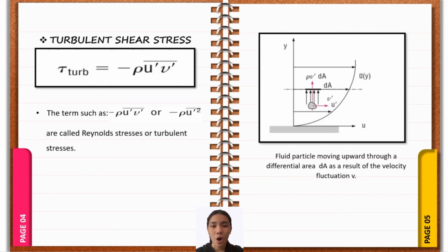Note that although the velocity profile is approximately parabolic in laminar flow, it becomes flatter or fuller in turbulent flow with a sharp drop near the pipe wall. The fullness increases with the Reynolds number and the velocity profile becomes more nearly uniform, lending support to the commonly utilized uniform velocity profile approximation for fully developed turbulent pipe flow. Keep in mind, however, that the flow speed at the wall of any pipe is always zero, the no-slip condition.